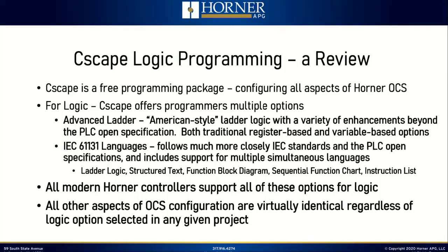Now, when it comes to logic programming, the intellectual property that tells the machine how to operate, that our customers and our OEMs program into the OCS using Cscape, you have multiple options. First, when Cscape was first invented back in the late 90s, it supported one language, and that was Advanced Ladder. So that's kind of an American-style ladder logic. And originally, that ladder logic was strictly register-based. So you had to manually assign every variable to a specific memory location.